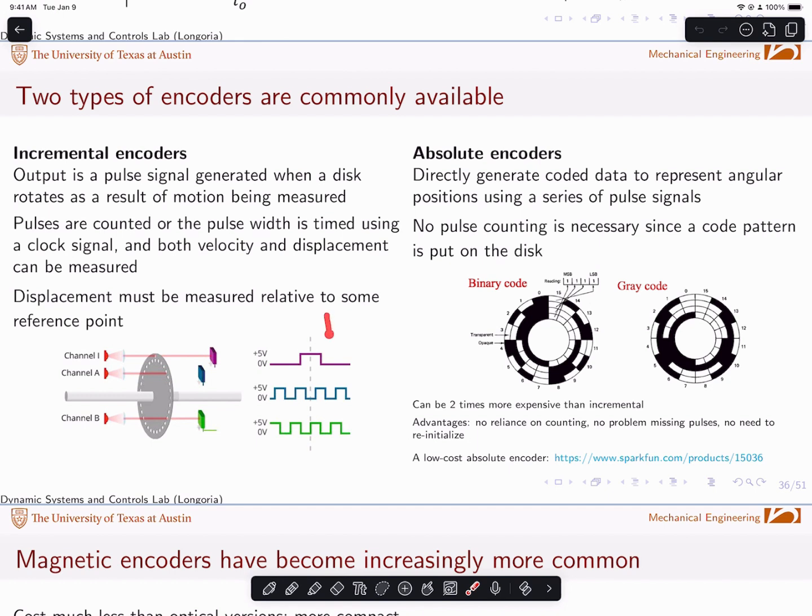So you might actually have designations for encoders that say how many pulses per revolution you can expect. It tells you how many lines or how many holes there are in that particular type of encoder. Incremental encoders work this way, and so they're okay for measuring speed, because all you have to do is measure the period, and you can allow timers to do that, to measure those digital type signals, right? You're not going to measure this with an analog A to D converter, for example. You're going to let timers do this, and there are some nice routines available, say, using an Arduino for doing this.